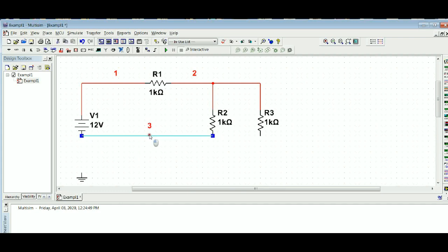Clicking that, and then if I select the wire, and you can see that my cursor turns into an arrow, I can pull it down wherever I want it, and it'll remain there. So suppose I'm in a situation where I need to come off a corner here. So what I can do is click in white space, and you typically won't have to do this. Sometimes I do, and that'll put a dot, and then you can come over here to set that, and then you can run this to where you're going to, and then we have our completed circuit.